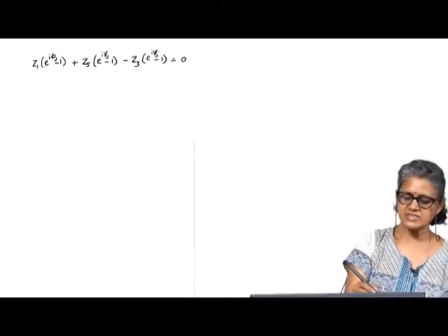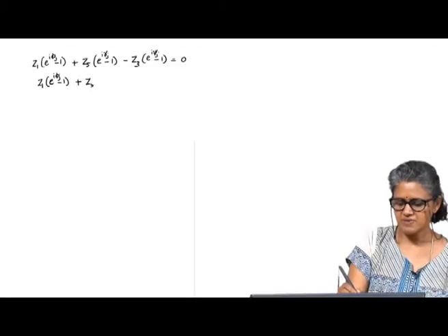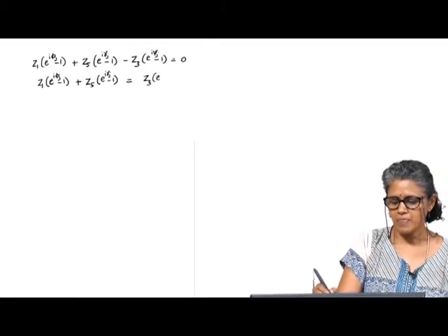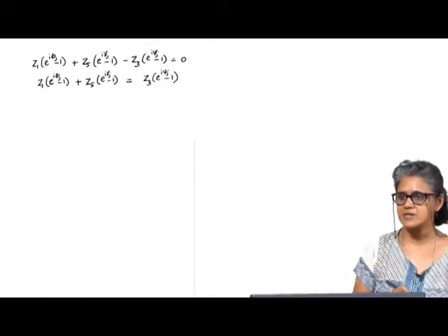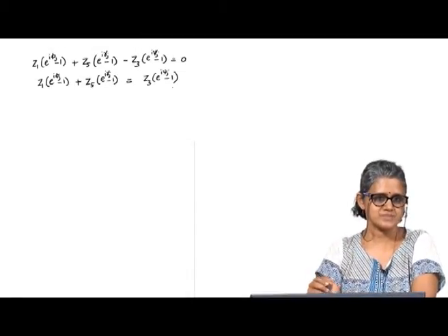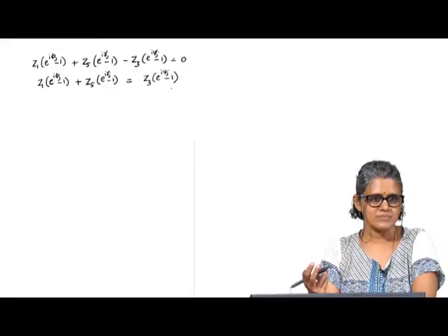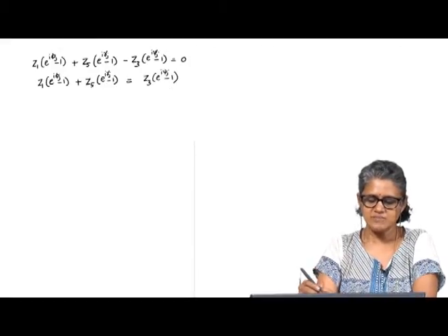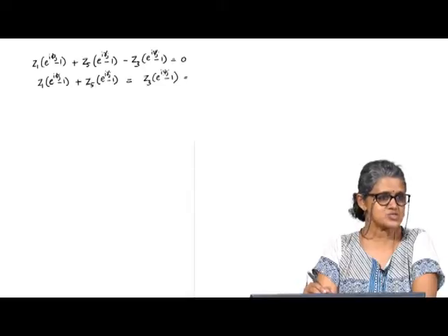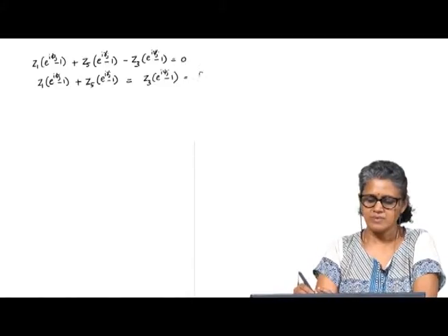I can rewrite this with the z3 term moved to the right side. Now, if I choose z3 as 2 of my free choices, to use up 2 of my 3 choices, and psi j is known because it is a function generation problem, I am given this. So, this right side becomes of the form delta j.